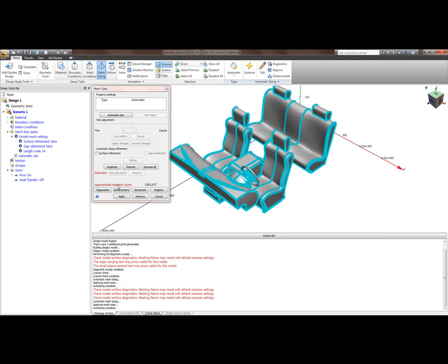So that's great. So this means my simulation is going to be a lot quicker, and I don't need that part because it's roughly 2 gigabytes of RAM for every million elements. So 6 for this is fine, 6, 7, and I've got enough in this PC that it will be covered for it.